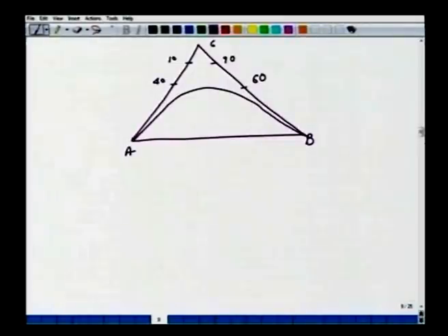In this case the raffinate phase concentration is given as 15%. So if this is 90 and 10 increasing in this direction, somewhere here we have to read this 85, and then read like this on the equilibrium curve.